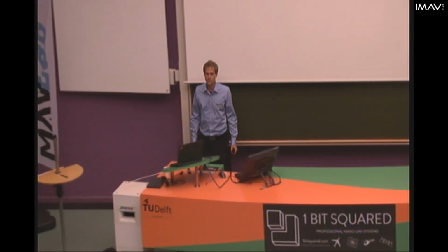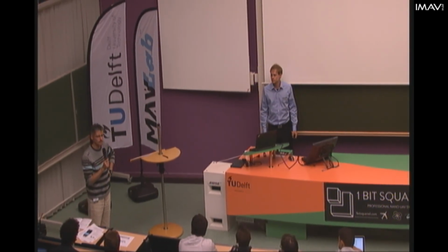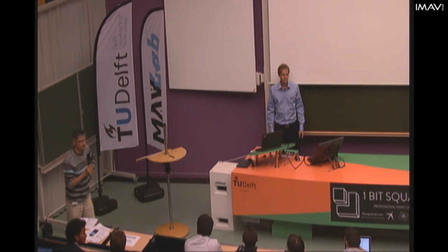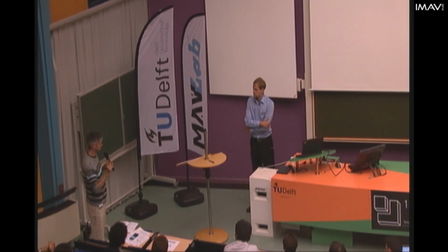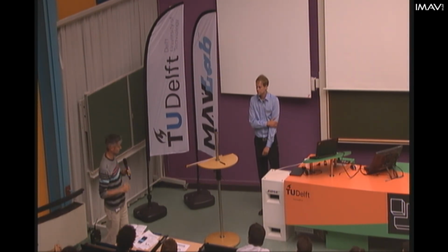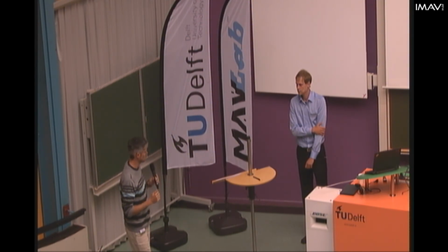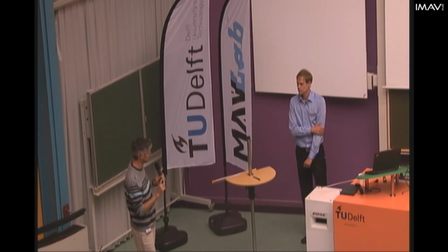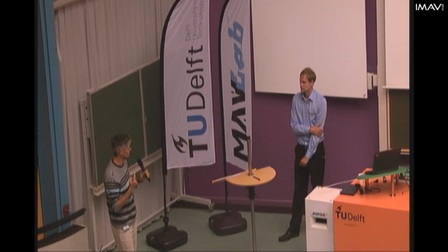Any more questions? We have plenty of time for questions. Okay, I may have one question. I believe your two rotors are contra-rotary to equilibrate the differential moments. And so when you are hovering, you are using the differential thrust to control the yaw, the roll. Yes, mainly. But then it should also produce a yaw. Of course, because they are different.